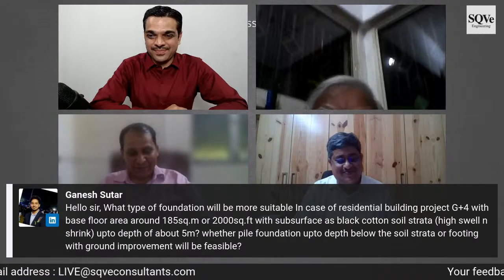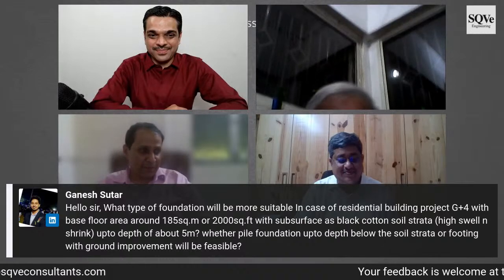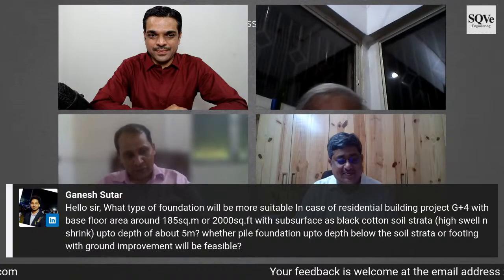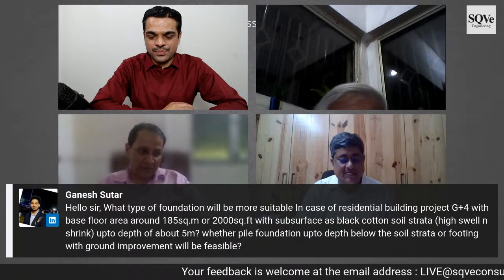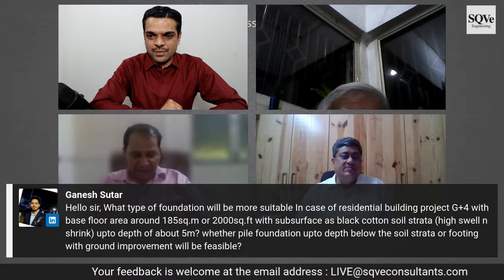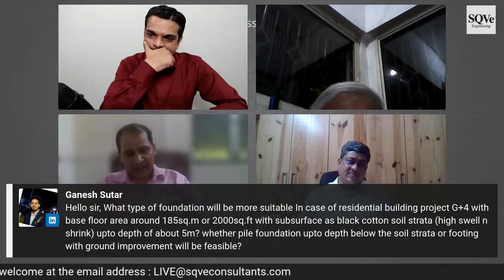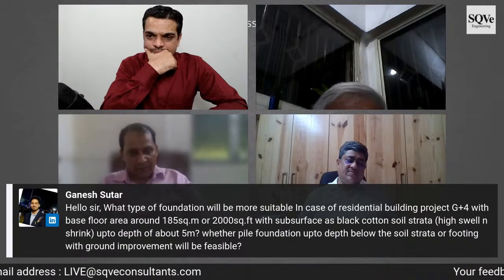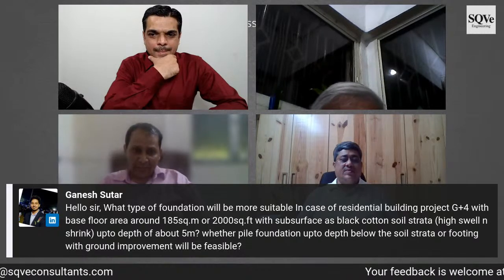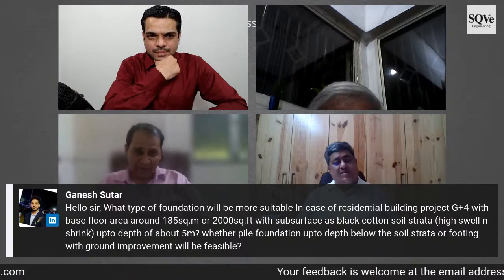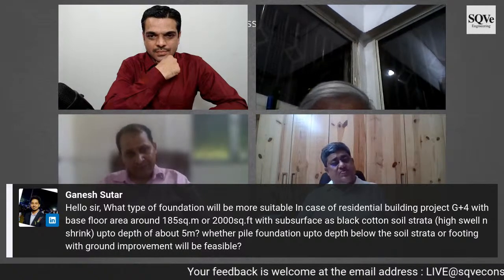Certainly, some amount of tension capacity needs to be developed so that at least the uplift friction component can be taken care of and the swelling characteristics can be resisted. Pile length will have to be increased in such cases. Yes, we did like that.